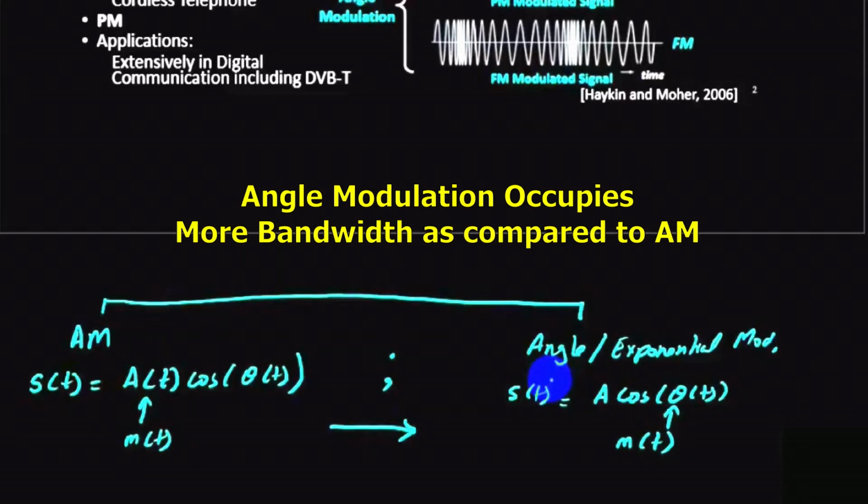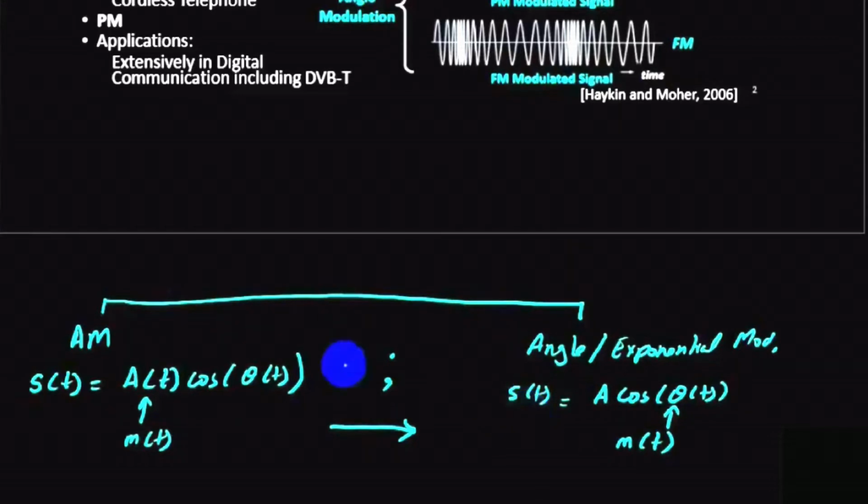Now, if we are going to lose on the spectrum by utilizing more bandwidth, what are the benefits? The answer to that is robustness, or what we call the resilience of the FM modulation scheme in terms of noise. If we are sending a signal over the air, because of the channel conditions and ambient noise of transmitter and receiver, the amplitude which governs the envelope, specifically for AM, may get attenuated or degraded.